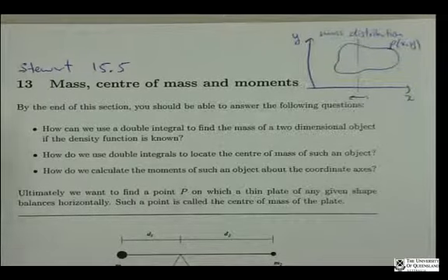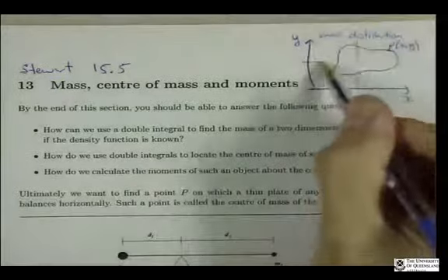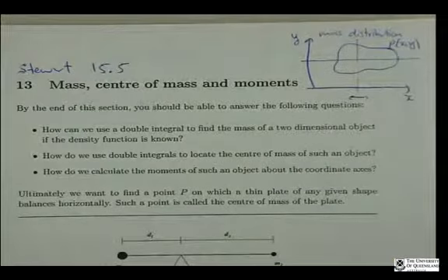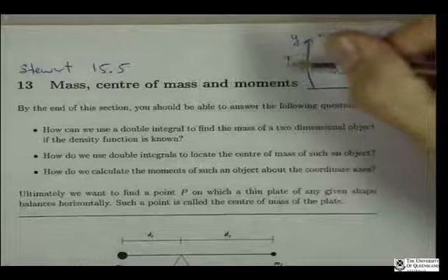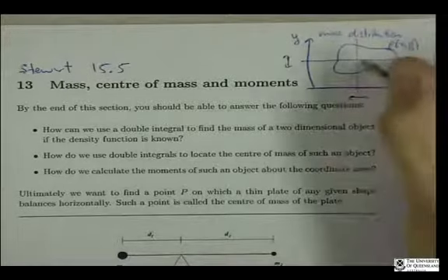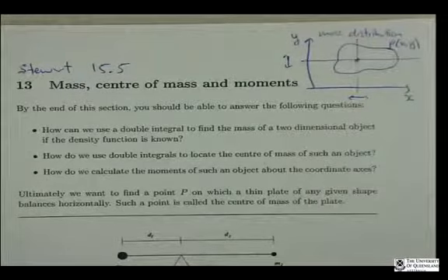And then we ask the same problem if we had a wire parallel to the x direction. We could ask, for what value of y could we place that wire? Or in other words, where could we put the two-dimensional object so that it balances on that wire? Now see this point where those two lines intersect. So we're looking for balance in this direction as well. And the point where those two lines intersect is called the centre of mass.